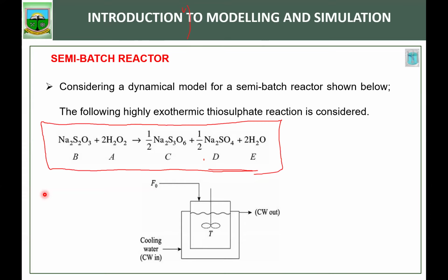Okay. Now, what's happening is that they have reactant B, and then reactant A. In this system, you will first put B in the system, then you flow A. A will flow continuously being added to B whilst B is consumed to form the products until the reactor reaches its required level. Then you stop flowing this.